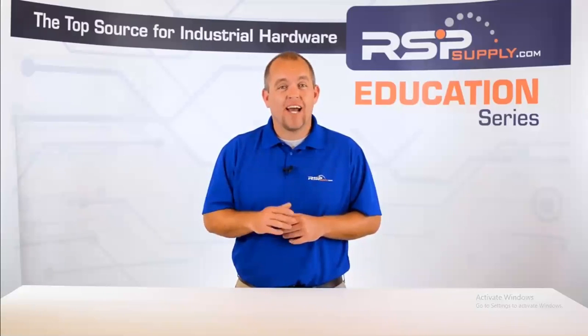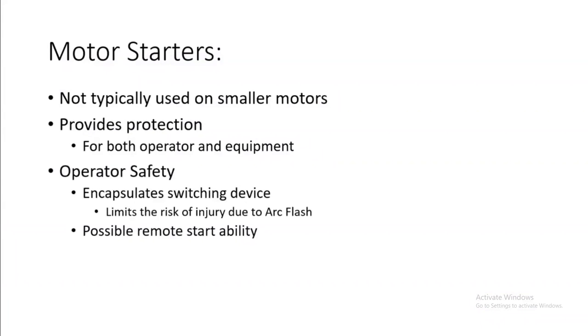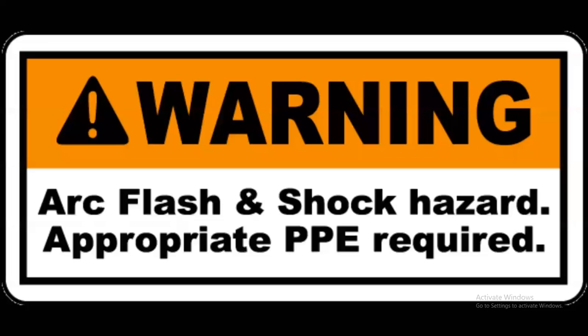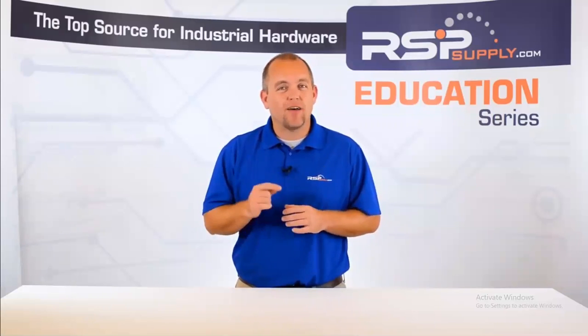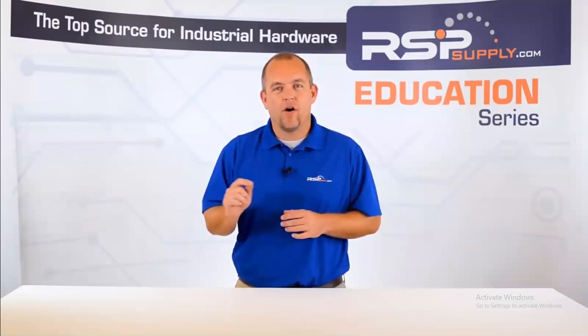First, let's talk about protecting the operator. In order to be able to turn a motor on and off, there needs to be some kind of switching device. If the power going to the motor is being switched manually by an operator, it can create all kinds of hazards, such as arcing, which can be very dangerous depending on the amount of voltage that is being switched. By using a motor starter, we can encapsulate the switching mechanism within the starter housing, which is a much safer method of turning the motor on and off.